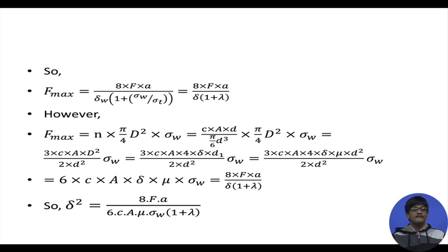So he will say that actually there was 1 bucket of water, and to that I added say half a bucket of abrasives. So you will say, fine, then that is the estimation. That means in 3 parts of slurry there is only 1 part of abrasive, so that the concentration comes out to be 1/3. And therefore we make an estimate now of the concentration from volume considerations.